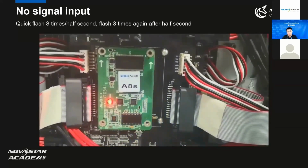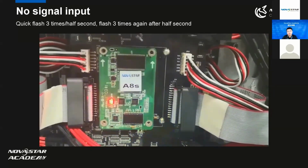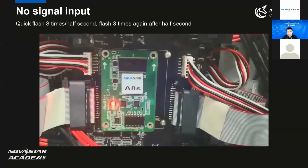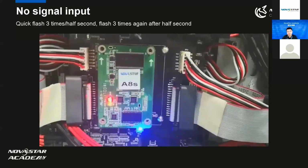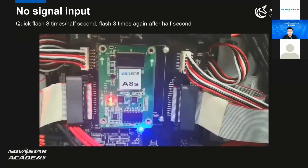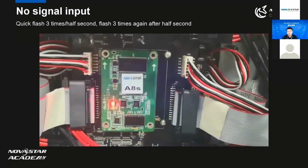But if the video signal is not fed to your system successfully, you will see the receiving card indicators flashing like this. The red light is still solid on, but the green light will flash 3 times in half second.